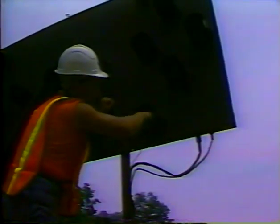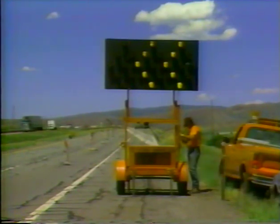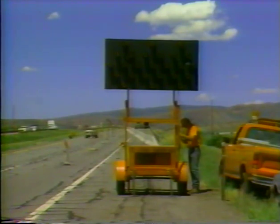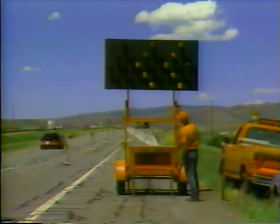Burned-out bulbs need to be replaced promptly so that these important devices can provide drivers with a clear, easily understood message. Most arrow panels have automatic devices that dim the lights during hours of darkness. Make sure it works. At night, an undimmed arrow panel is bright enough to blind approaching drivers.